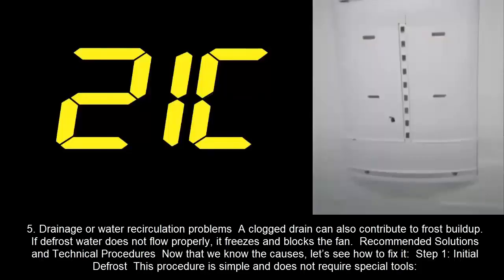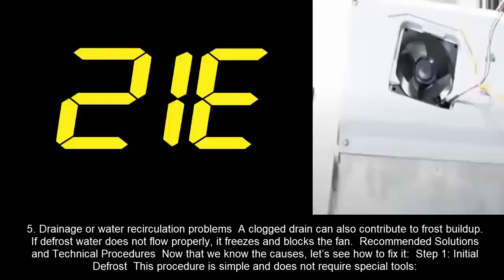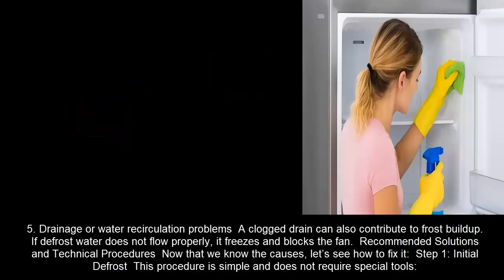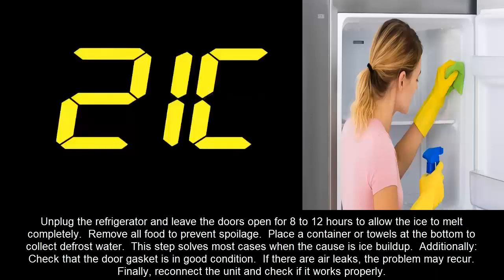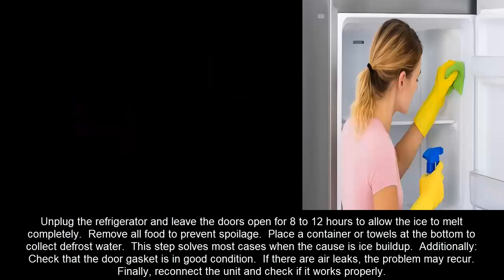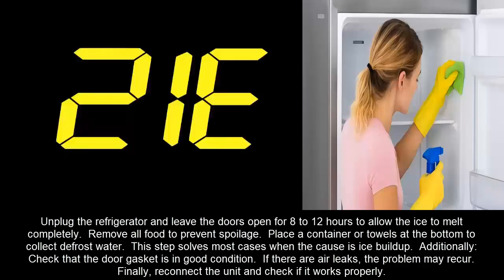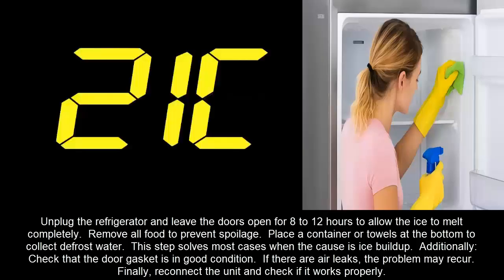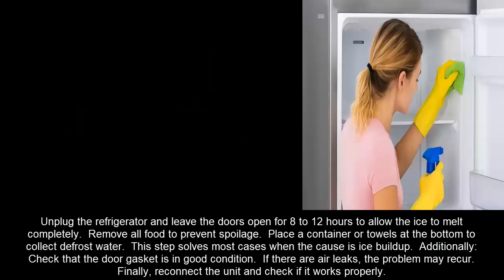Recommended solutions and technical procedures. Now that we know the causes, let's see how to fix it. Step 1. Initial defrost. This procedure is simple and does not require special tools. Unplug the refrigerator and leave the doors open for 8 to 12 hours to allow the ice to melt completely. Remove all food to prevent spoilage. Place a container or towels at the bottom to collect defrost water. This step solves most cases when the cause is ice buildup.